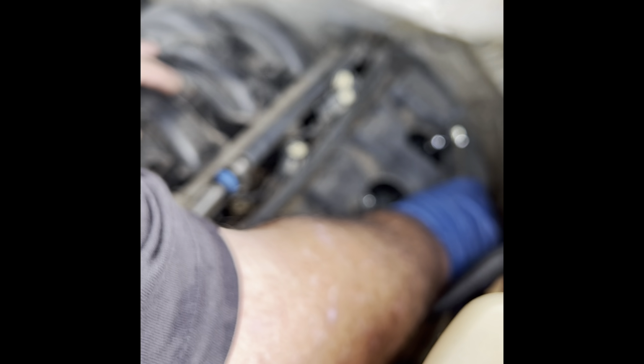Now I'm going to go back to this. I recommend that everybody torques their spark plugs to the correct OEM specs on a torque wrench. I've been doing it long enough that I know what the feel is for the torque on these. So if you're gonna do it yourself, you've never done them much, get you a little torque ratchet. You'll use it a lot if you're working on cars.